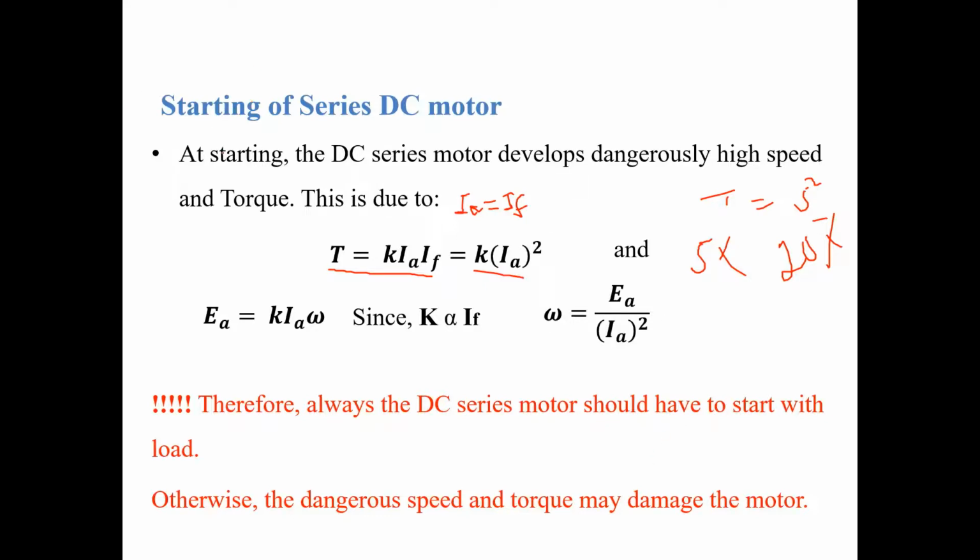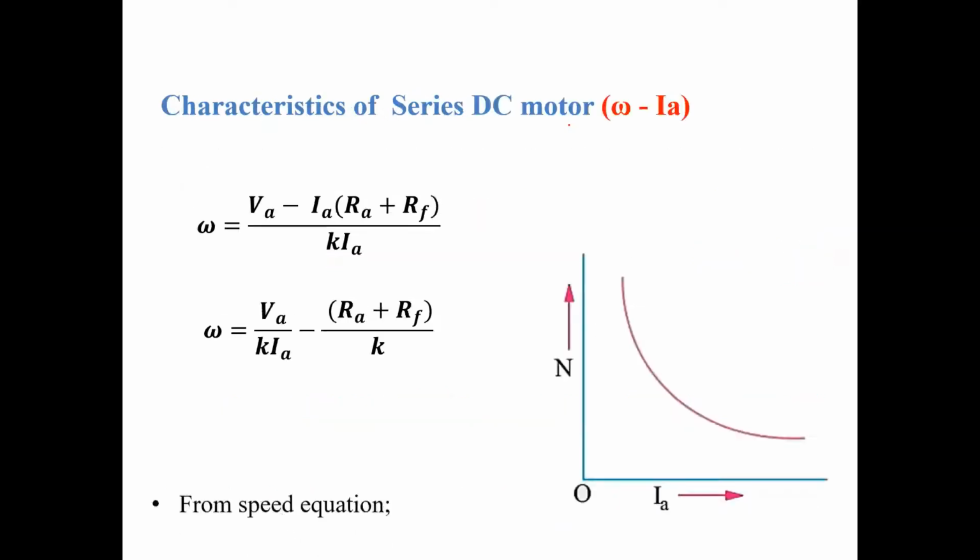At starting of the series motor, always connect a load, then you can start the motor. Otherwise, it is very difficult to start the series motor. So these are the starting precautions of the series DC motor.